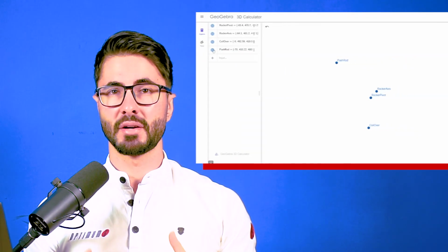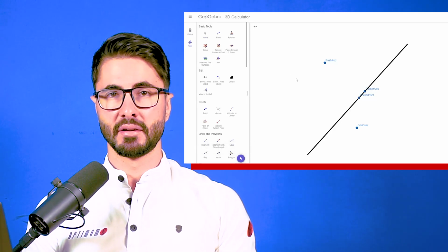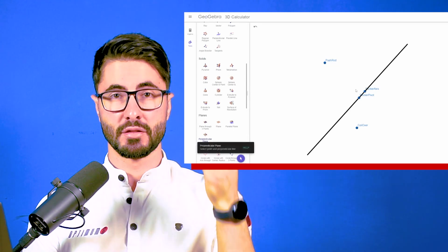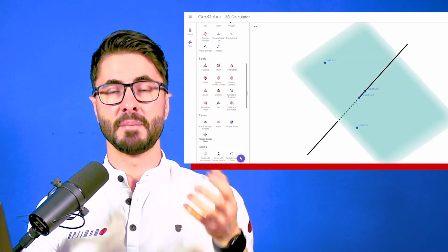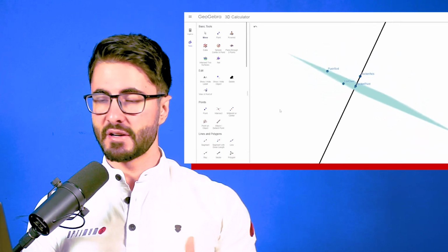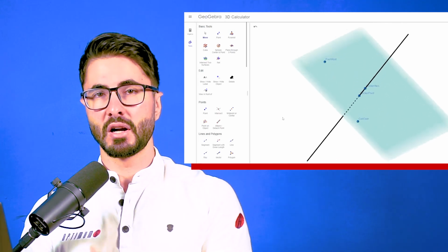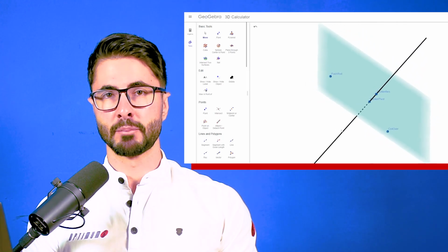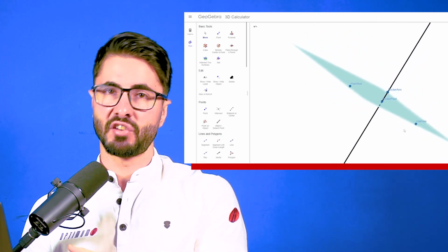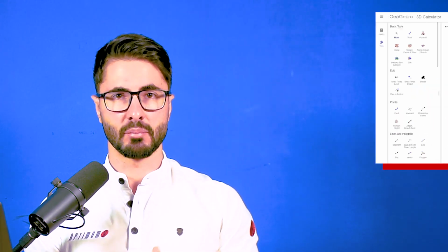In order to make sure that all the pickup points are on the same plane, you can use, for example, a CAD software. In our case, we're using a simple geometry tool where we can first define the plane of the rocker by defining its 3 pickup points, and one of them being the pivot axis, which must be perpendicular to it. And then after that, we can look at all other pickup points for the push rod, for the rocker, always making sure that they're on the same plane. So throughout this exercise, whenever I make changes, I'm always going back to this tool in order to make sure everything is on the same plane.